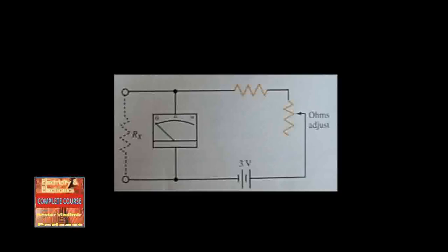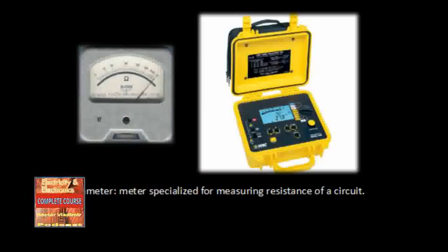Part of this resistance is made up of a variable resistor to allow the total resistance to vary. Because temperature changes or weak batteries can affect the total resistance of the circuit, the ohm meter must be calibrated. Adjust for zero resistance in order to ensure the most accurate reading possible. The knob used for adjusting the pointing needle position to zero is usually marked zero adjust or with an omega symbol